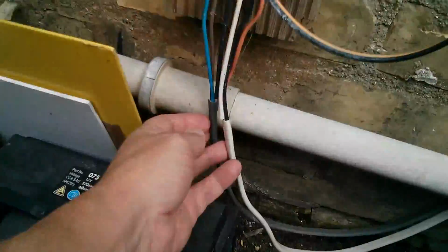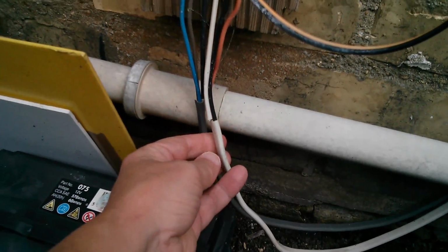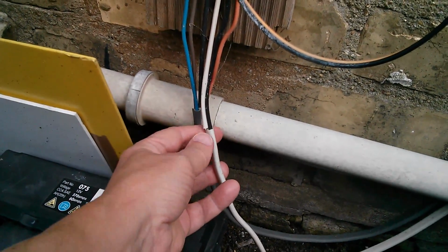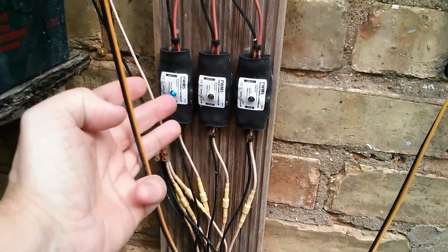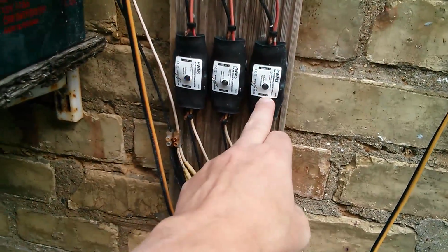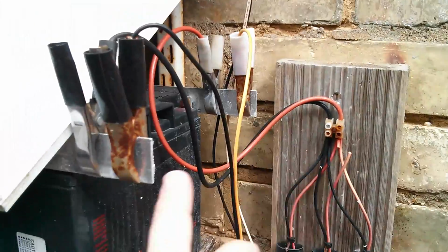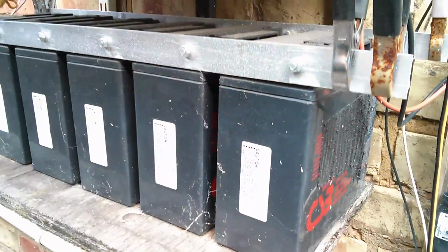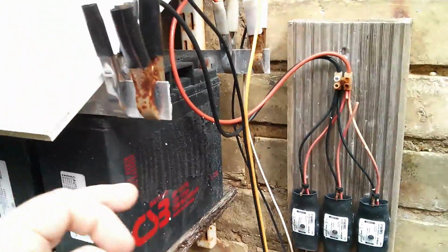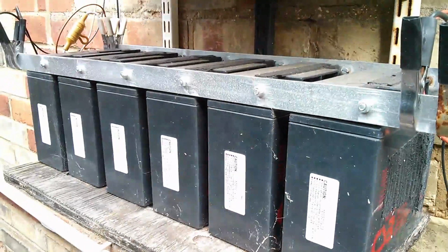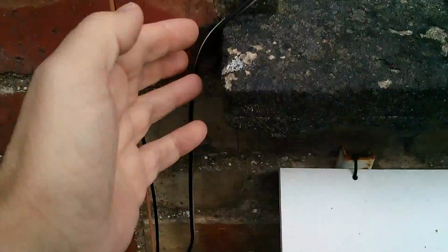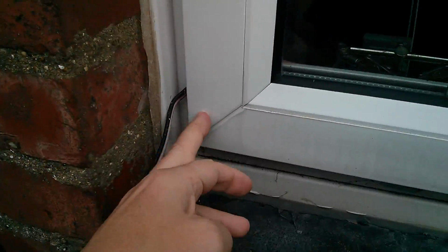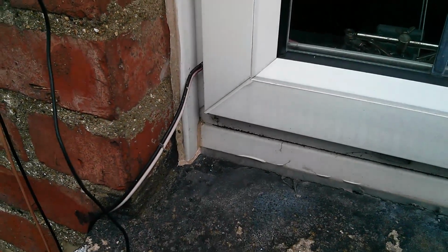Now this system has these very thick copper wires. This is I think 20 amp or 15 amp twin and earth coming onto this panel with these charge controllers, two of which now I don't think work. I think only this one is working, and then connected to my batteries, which are just outside the workshop window. Batteries paralleled up, and then 12 volts from this system is tapped off here through a fuse and then runs through this wire through the window and into the workshop.